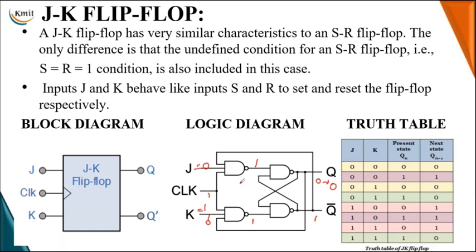Next, if present state is 1, then due to this 1 input, the second NAND gate output now becomes 0. When it becomes 0, this 0 input on your fourth NAND gate will transfer the complemented state with logic 1, and this is transferred as one of the inputs of your third NAND gate. Earlier you assumed your present state is 0, but now present state is 1, so the complemented state becomes 0.